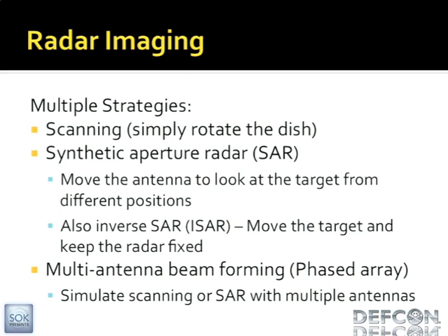We've gotten a little bit more sophisticated than that since then. There's something called synthetic aperture radar, which basically means you can get better resolution if you have a bigger dish. But the bigger dishes are more directional, so that's the advantage. With synthetic aperture radar, you're taking coherent measurements of the signal at different places, and you're trying to simulate having a larger dish. The reason you would do that is so that you can get a finer resolution of space. If you just point it in one direction, I think the beam widths on these things are 40 degrees or something, so you couldn't see anything out there.